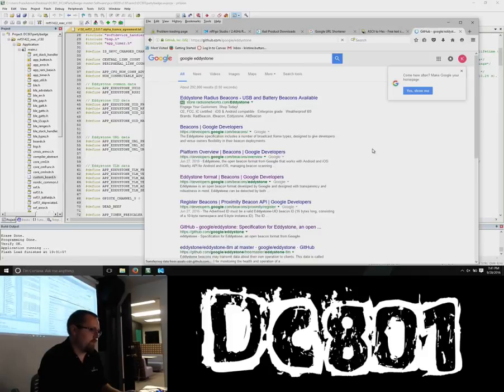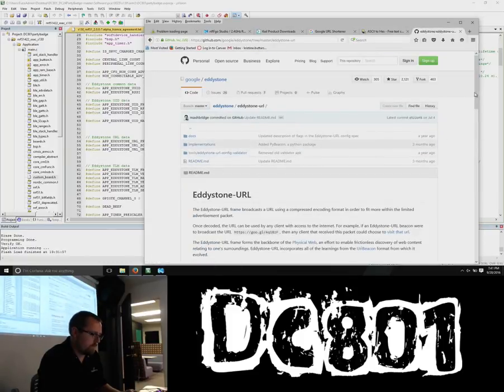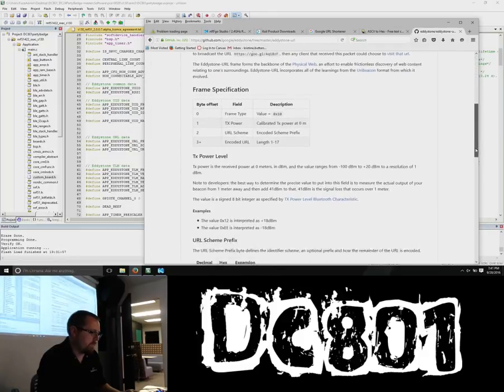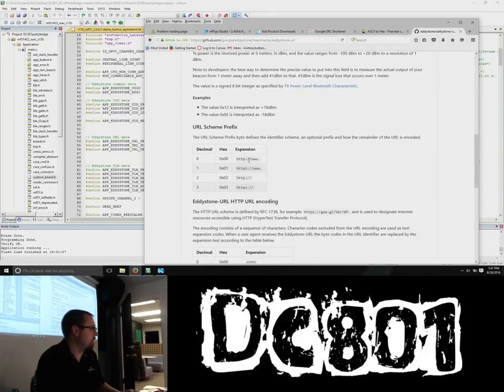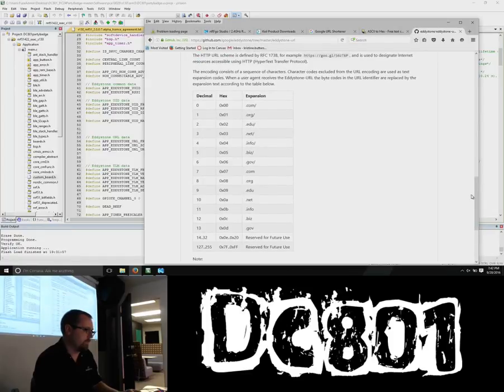On GitHub, there's Eddystone, and then Eddystone URL, and this will go through. So 00 is http://www., 01 is https://www., 02 is http://, 03 is https://. So you don't have to do any of that in your hex. It auto does it with the upper value. And then for different endings, they do have special codes to go with it as well, if you want to do it with the ending.